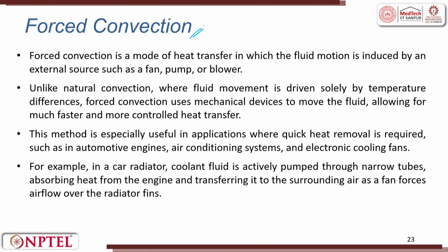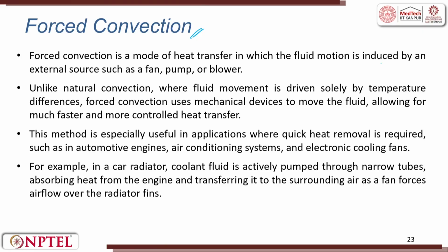So, now let us move to forced convection. So, hot body, cold air, warm air. Now, this is happening naturally. Now, I force air. Forced convection is a mode of heat transfer in which the fluid motion is induced by an external source such as a fan, pump or a blower. Unlike natural convection, where fluid flow is driven solely by temperature difference, forced convection uses a mechanical device to move the fluid, allowing a much faster and more controlled way of heat transfer.